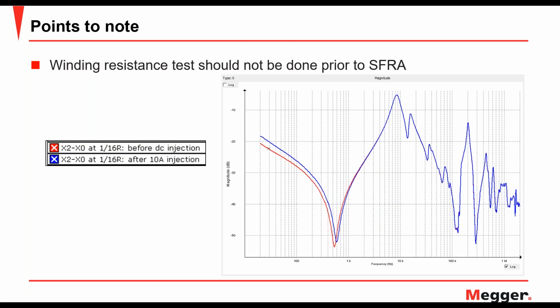And then you have the magnetism in the core. I spoke about how magnetism in the core can influence measurements, and the deviations resulting from it are typically observed in open circuit measurements, where the core has an influence in the low frequency range. One way of inducing magnetism in the core is by doing a winding resistance test. In a winding resistance test, a DC current is injected into the winding, and that sets up a unidirectional flux which magnetizes the core. The coil loses its inductive properties, and what we are left with is the resistance of the conductor, which is then measured by the test set.